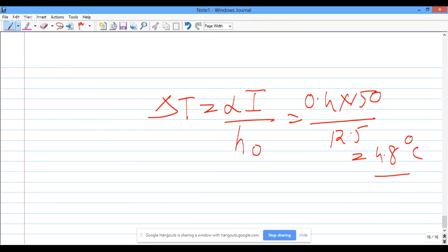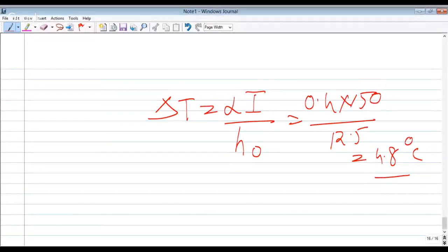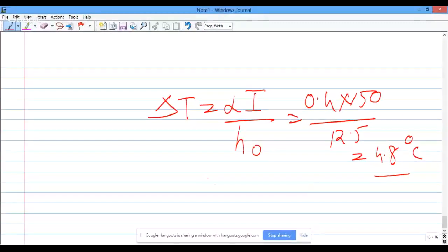But I want to find out the heat flow due to this. In steady state, of course, this is all steady state I'm talking of, that will be U into area of the wall into 4.8. So if radiation is falling on an opaque surface, this is what it will be. Okay, so this is how you can calculate the heat flow coming into a building under steady condition. Is there a question in the meantime?